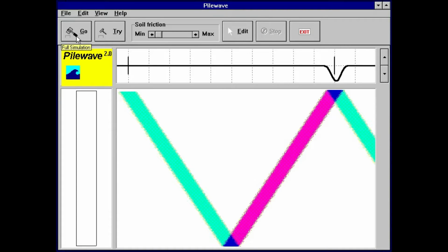And what I get, this area which is in cyan is compression, and this which is in magenta is in tension. And basically, let me go ahead and change the view to GRL just to make everybody happy. Basically, when you strike a pile or drill shafts with low or high intensity impact, you get a compressive wave going down. And it gets down to the toe. If the toe is free, it has no constraint on it at all, let's say minimal or no constraint at all, it will return as a tension wave.